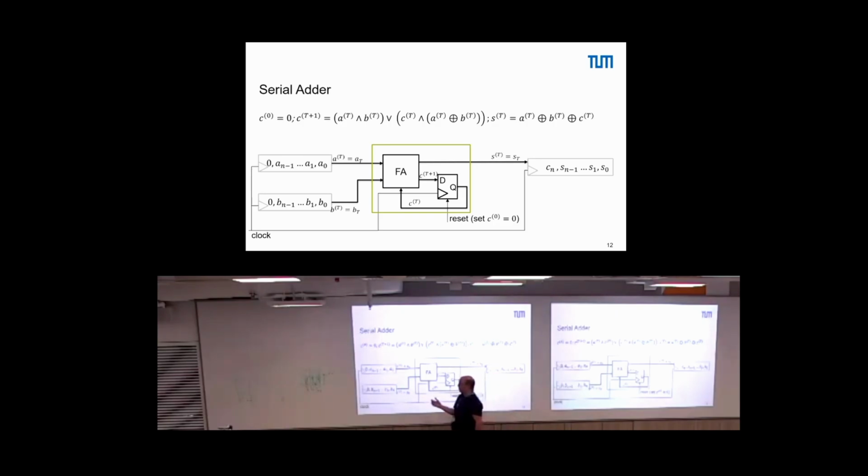Applying the ripple carry adder would have this long critical path, so you decide to go for the serial adder. Now, what happens? Your processor loads this into a register, and then your processor that has to run on a gigahertz clock waits for 32 or 64 clock cycles, doing nothing but waiting, because your adder requires this time budget to compute the result. That's why it's bad. It's not bad for each and every individual architecture, but it's definitely a downside.